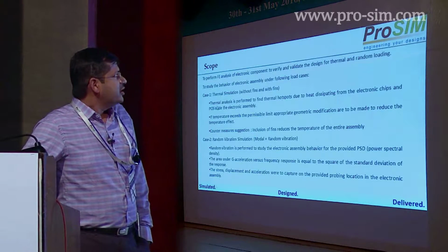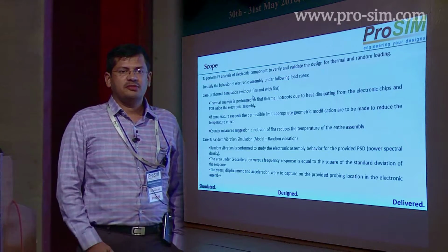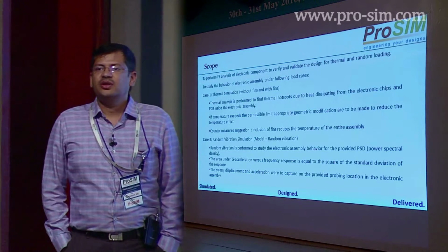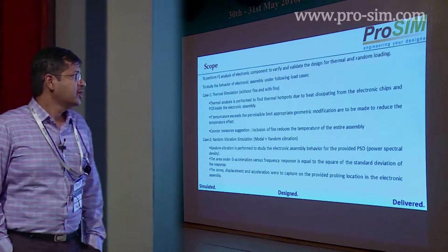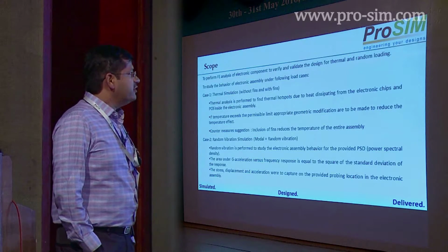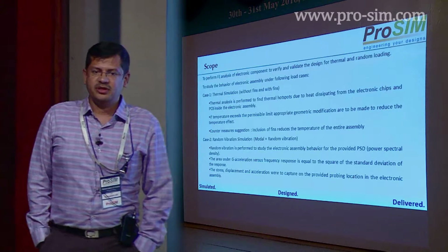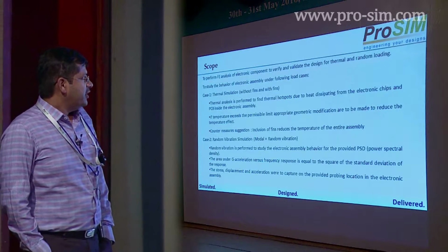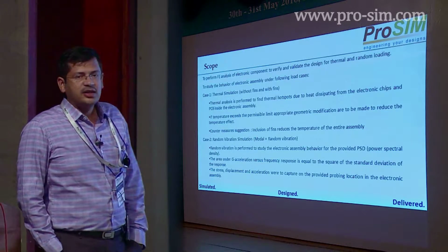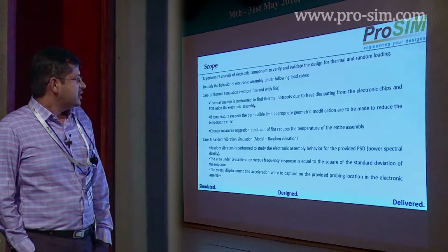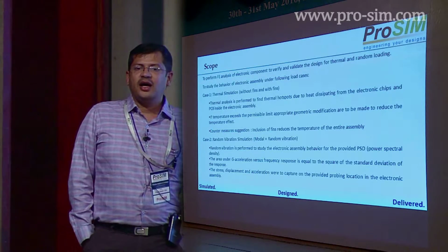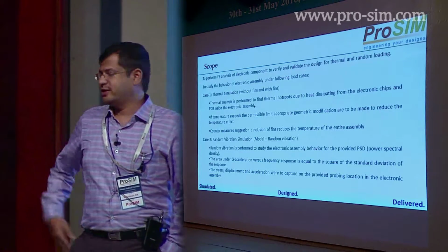In the first case, we will be identifying the thermal hotspots and working on the reduction of temperature based on countermeasure suggestions. And in the random vibration simulation, we do modal and random vibration response analysis, studying with the customer provided power spectral density curve, and also outputs such as stress, displacement, and acceleration at 3 probe locations as suggested by the customer.